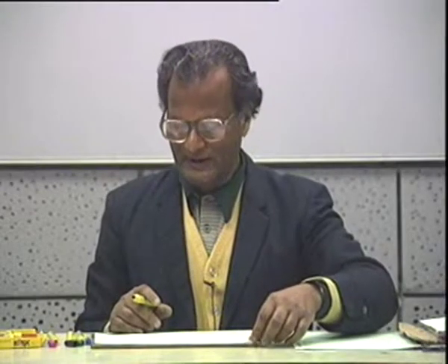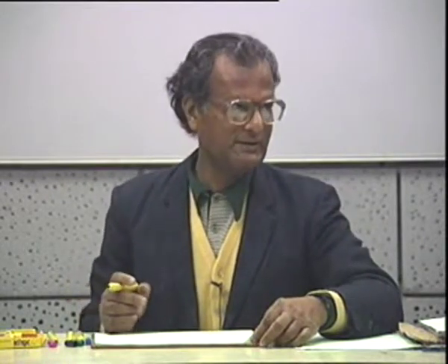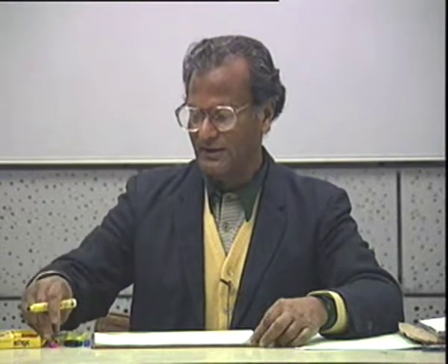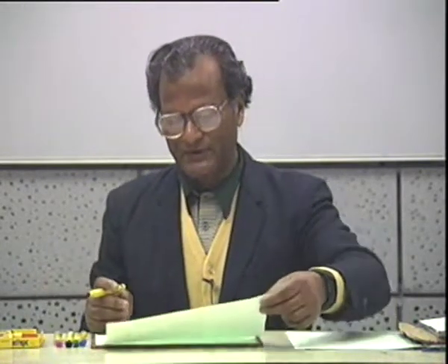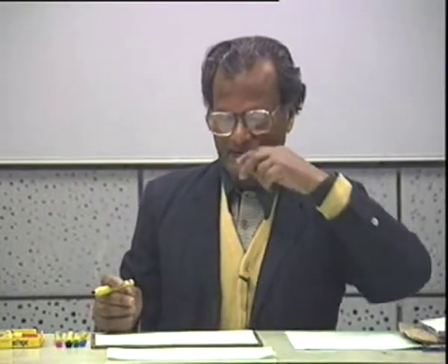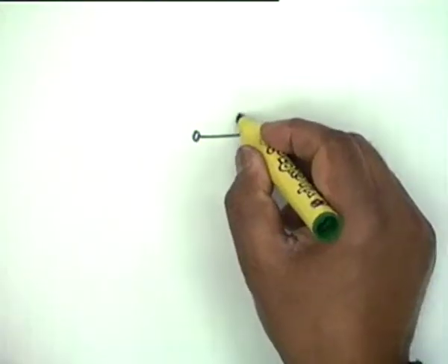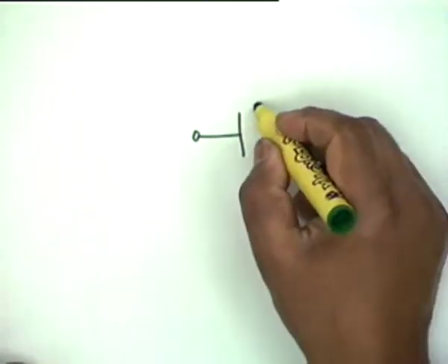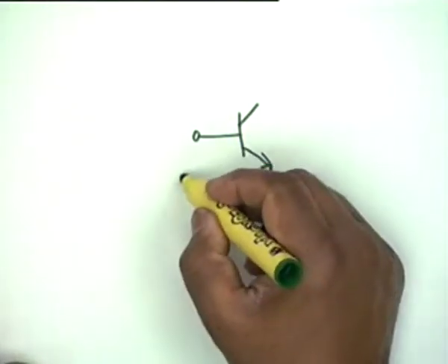We are going to look at the class A power amplifier and calculation of efficiency, both in class A and also in class B and class AB under some idealized assumptions. If you recall, the class A power amplifier circuit, a very simple circuit that was drawn yesterday with integrated circuits in mind, that is, we use the minimum number of resistors and as many transistors as is required.